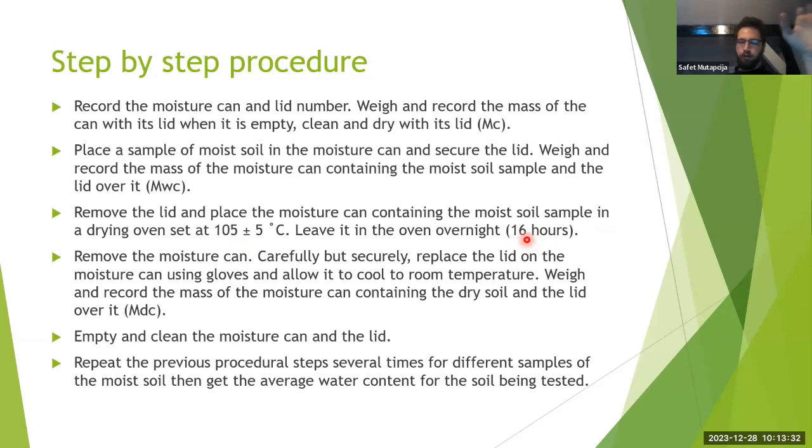But if you have really moist soil or organic soil, sometimes it is needed to have it more than 16 hours. I usually do 24, but when I did my master thesis on soil mechanics, I used to leave it there for like 48 hours just to be safe. But that's not something that you're going to do in your laboratory if you're not doing any research, because every time it's like, oh, it needs to be as fast as possible because you have other samples, you have your deadlines, and you're going to leave it just 16 hours, you will be fine.